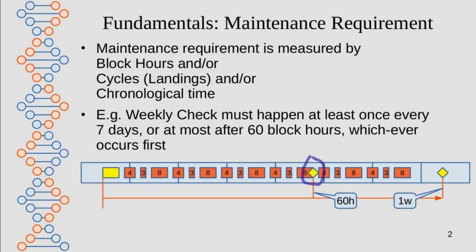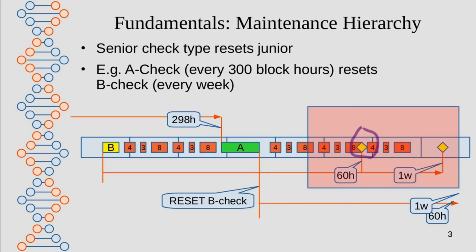Down each aircraft, it accumulates 3 utilization measures for each check type, since the last effective date and time for the previous check. In places where the next check is not planned within the maximum allowed utilization specification, the required check is flagged with an expiry marker on the chart. The marker is a visual hint to the maintenance planner to add a suitable check prior to its appearance.